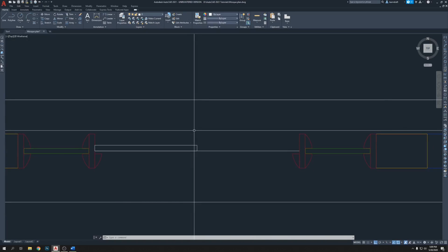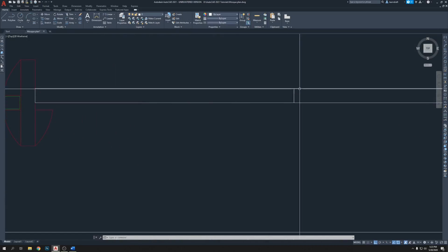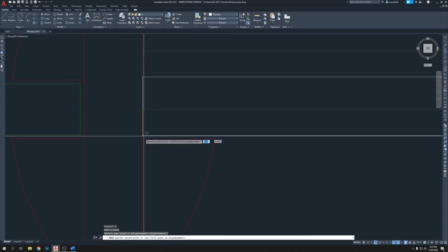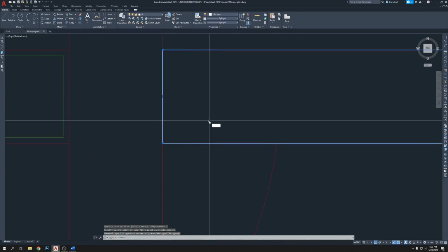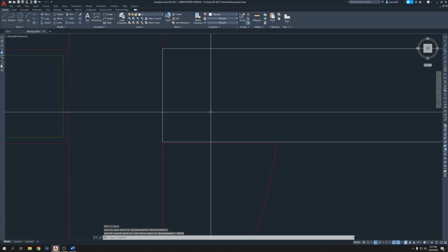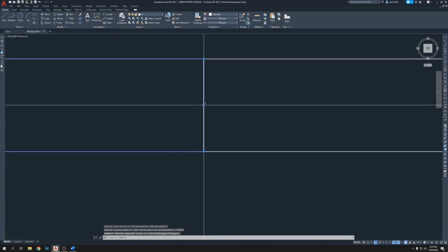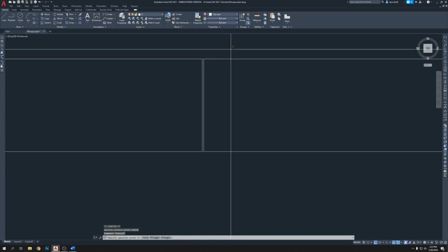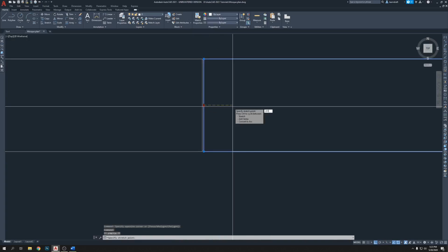Okay. We are going to work on the main door now. So let's bring it a little closer. It's just too far. Select both of them. Move from here to there. And I'm going to make some space, maybe 1/16. Move 0.03125. And the gap is going to be both ways, 0.03125. Enter. 0.03125.